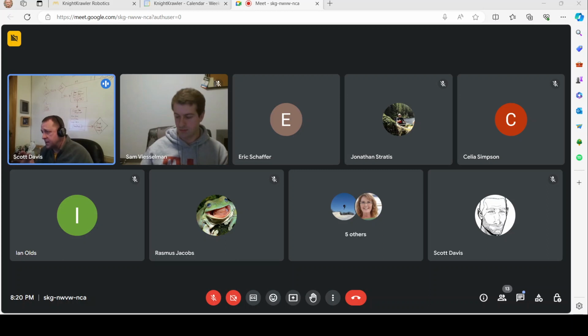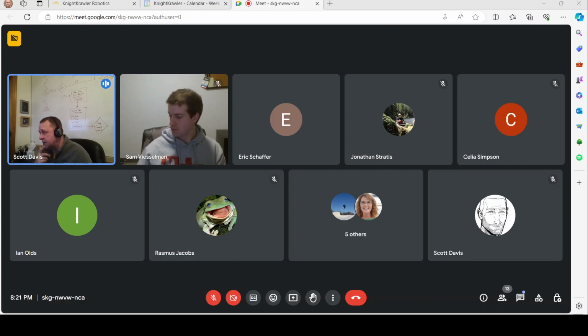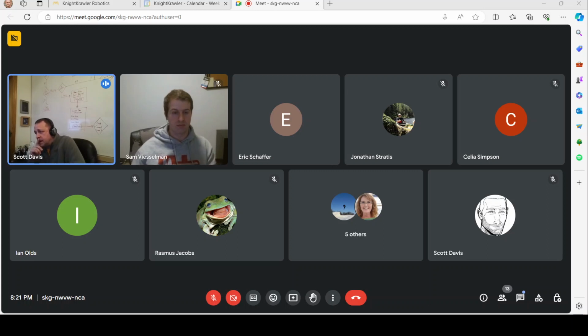He was also doing April tag with some type of custom, not Photon Vision, image in the fall. Then he ran into an issue where the latest WPI version would not trust it because it wasn't an official image or something. And we switched to Photon Vision. I think that's what he told me. So since we're going to be doing raw calculation, we may go back to his custom image he found and was using in November and December. All I know is that Caleb has said the plan is that we're going to start doing manual filtering on the RoboRio position calculation.